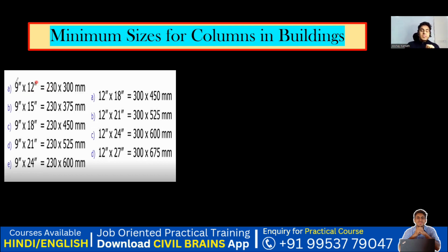Next, if this column is failing, you can go with 9 inch by 15 inch, the next standard size. We don't have a size of 9 inch by 13 inch. We go with 9 inch by 15 inch. Then we have 9 inch by 18 inch. Then I can go with 9 inch by 21 inch. Then I can go with 9 inch by 24 inch. These are standard dimensions that we can adopt.